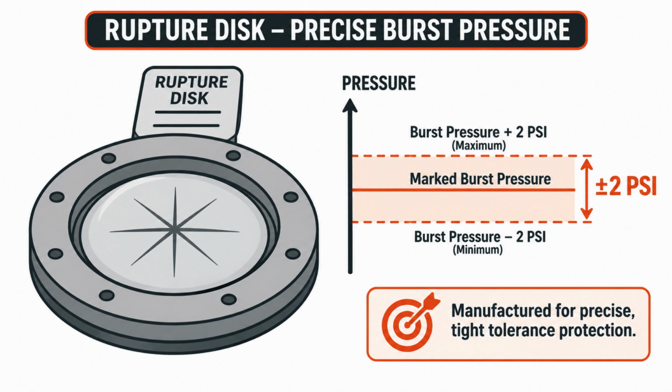Quick recap: relief device design now lives in Section XIII, while UG-150 through UG-156 covers when and how much protection Division 1 vessels need. It's the user's responsibility to size and install it. Standard overpressure limit is 10% or 3 psi, fire exposure allows up to 21%. And several device types, alone or combined, can satisfy the requirement.